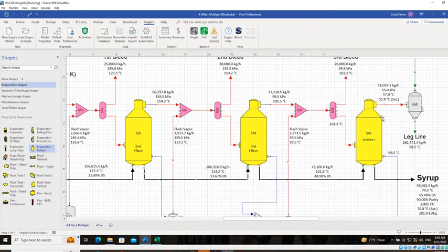There's also all of the detailed physical design elements of the evaporator itself. So the flow rate through the tubes, assuming it's a forced circulation type. If it's a plate type, then you need to know the distances between the plates and the film thickness of the juice flowing over the surfaces.